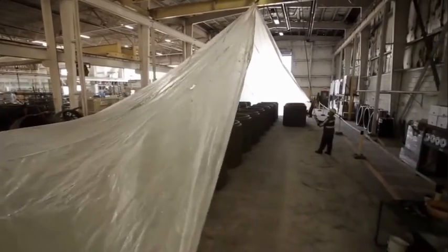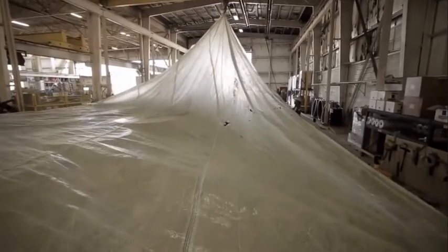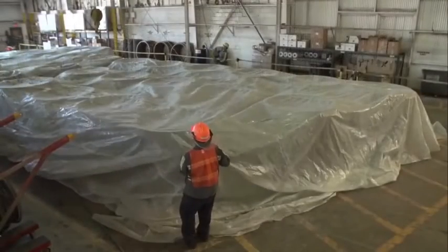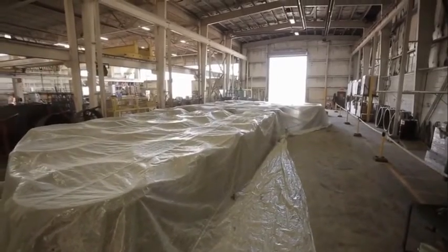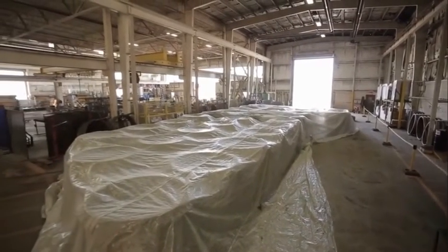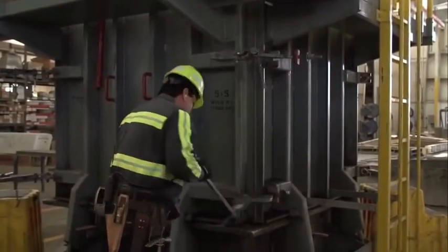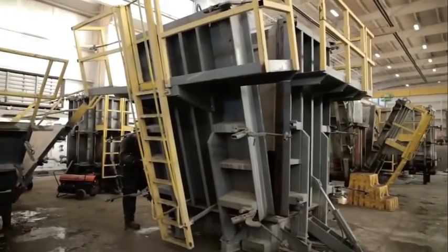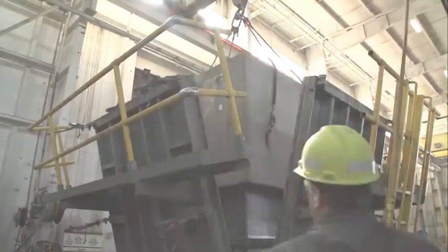The controlled environment of a precast factory enables the product to properly cure and reach the full design strength. Once the QC technician confirms that the product has reached the desired strip strength of 2,500 to 3,000 psi, then the stripping process may begin. This involves opening the outer jacket, collapsing the inner core, attaching the lifting devices, and removing the product from the form.